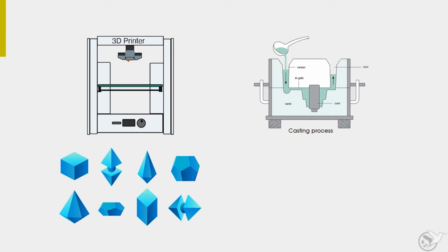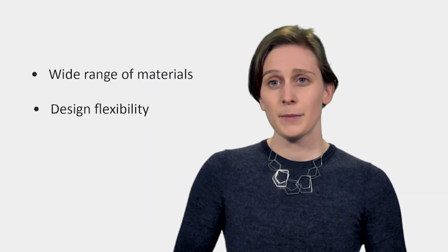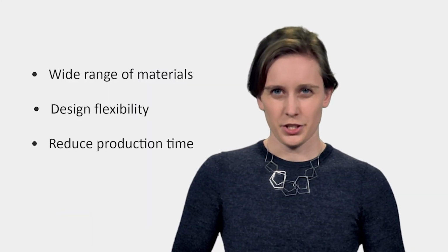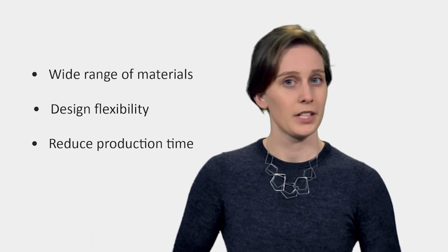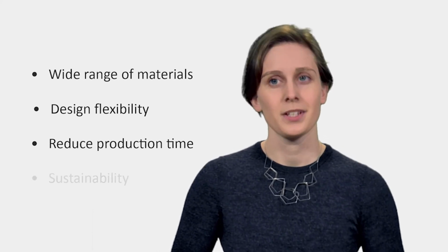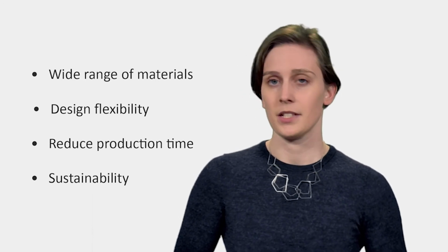This flexibility also means that a single printer can produce a virtually infinite number of parts and designs, as opposed to a process like casting where a unique mold has to be created for every individual design. Additive manufacturing can also greatly reduce production time. Designs that could take even a highly skilled technician a few days to produce can now be printed in a matter of hours. It can also be considered more sustainable, since little to no material is wasted in the production process.